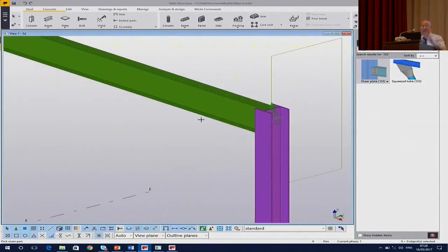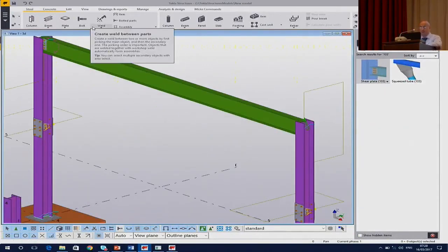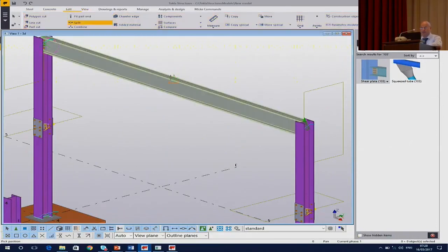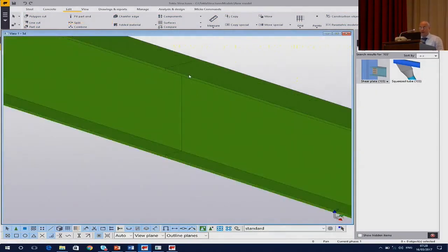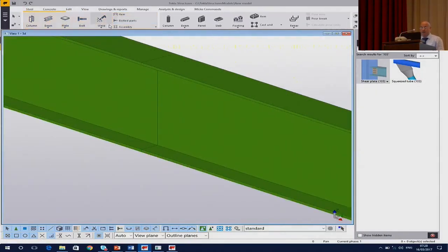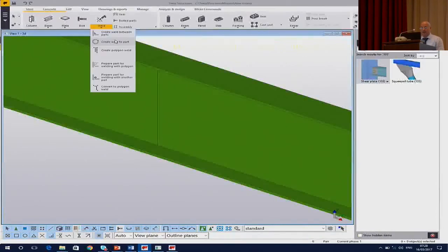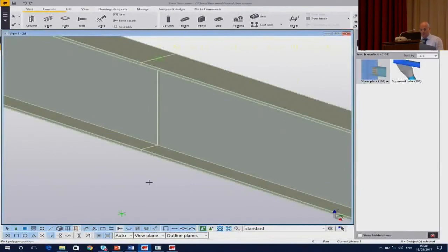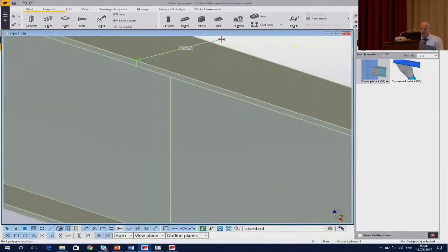And then what we'll do, this time I'm going to weld those two. I'm going to actually split this. So I'll say, okay, let's edit, split this. So it's two pieces like so. And then I'm going to weld these two together. So now I'll say steel, a weld in there. It's what we call a polygon weld. That one welds to that one, and the weld goes from that point there to that point there. That's a typical little weld.